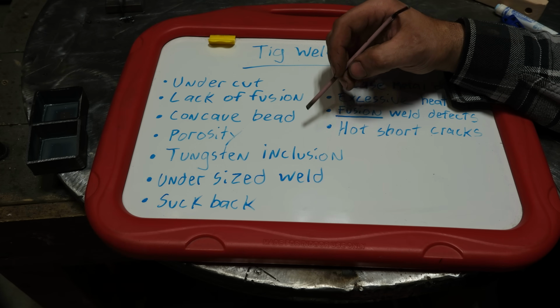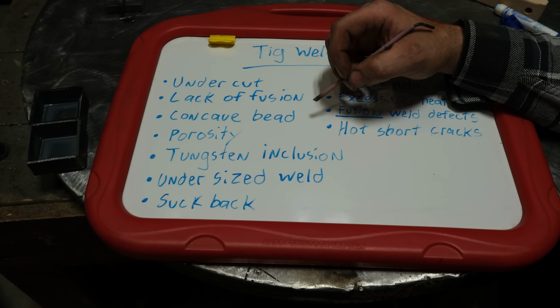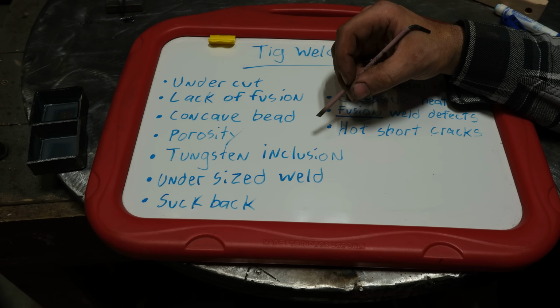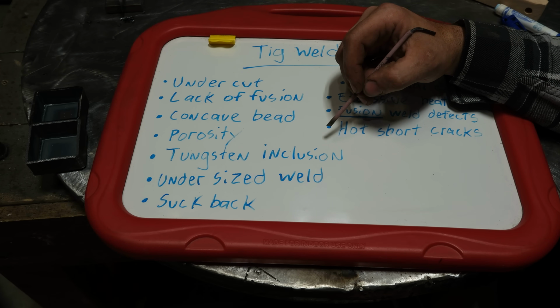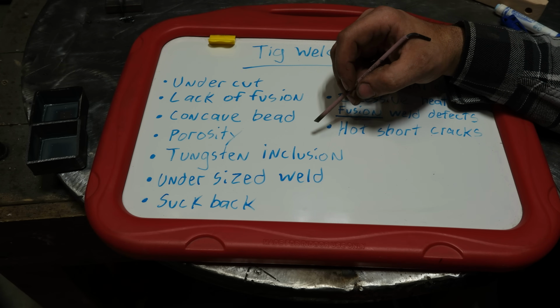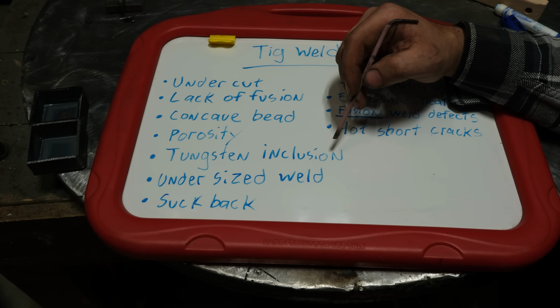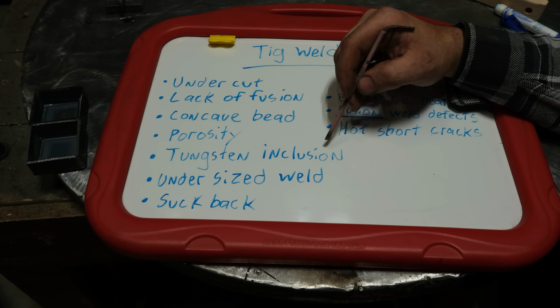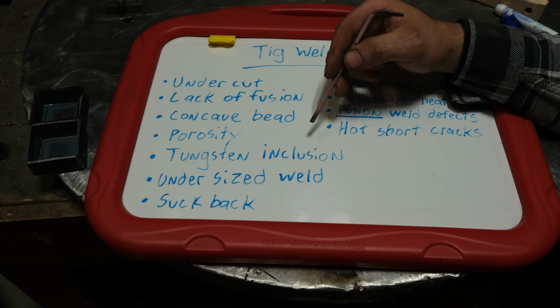You have an inclusion that is not going anywhere. It can't be welded out. The only way to remove it would be to grind it clean and then weld over clean material. Now, is this a significant concern? If you're building yard art, absolutely not. It really isn't going to make any difference.